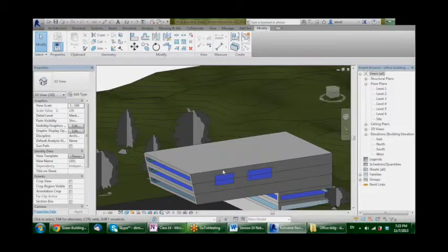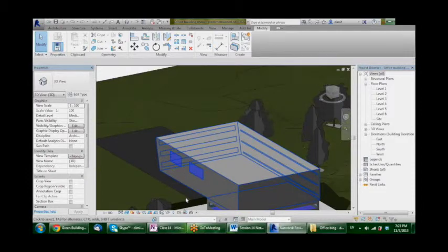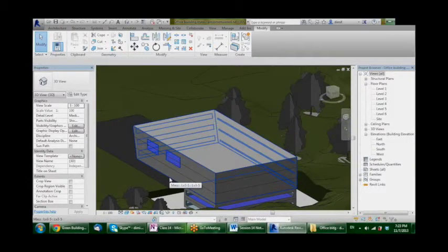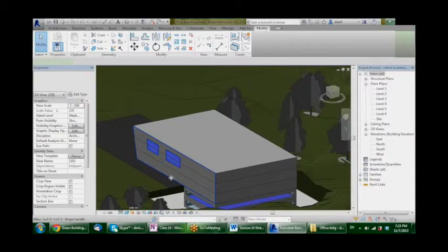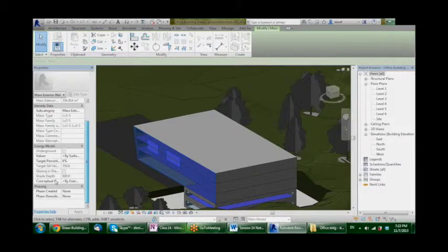In terms of conceptual constructions, you can also do the same thing for your walls. So let's say I want this wall to be a different type from this wall. Again, hovering your mouse, tab button, you select your wall, and you see the conceptual construction showing up here again.